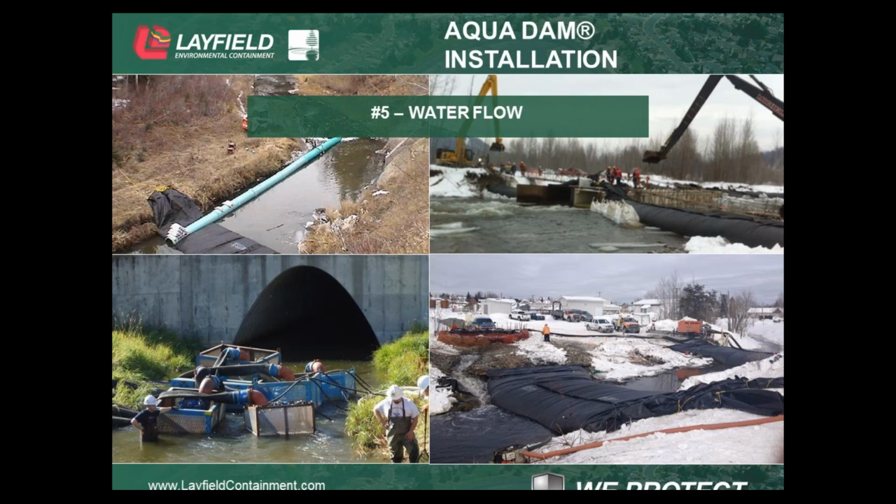The bottom left picture, we've got six submersible pumps that are going to divert flow around the work site. So prior to the installation, we're actually going to turn those pumps on, because we want to start diverting the flow before we actually install it, because as you can see, six submersible pumps, 8-inch in size, there's a substantial flow there. The second we put the aqua dam across, we're potentially going to be washing out that aqua dam if we don't have those pumps on before we start actually installing the aqua dam. So that's something we need to consider during the installation process, is when do we turn those pumps on. Generally speaking, it's going to be before we start the installation of the aqua dam.